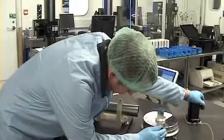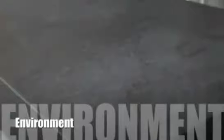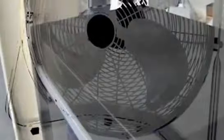So first, to check the fixturing. Normally I just touch the back of the autocollimator or the fixturing it's sitting on and seeing if that affects the reading of the autocollimator. Environment, what we're looking for here is temperature gradients or air turbulence. What we don't want is things like fans, open doors, affecting the light path of the autocollimator.